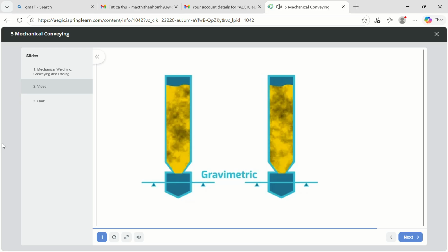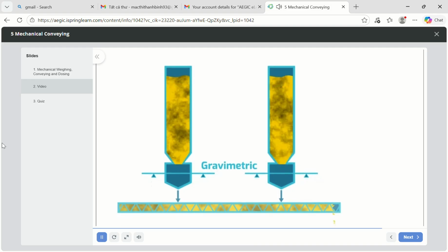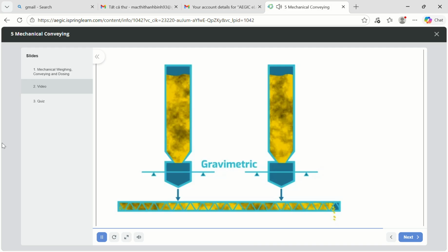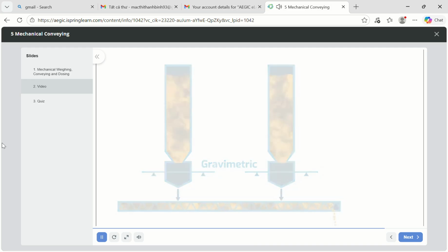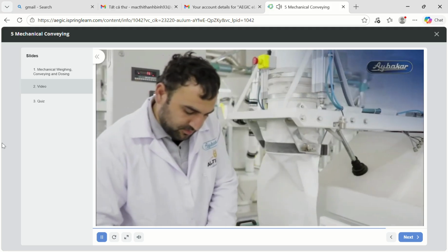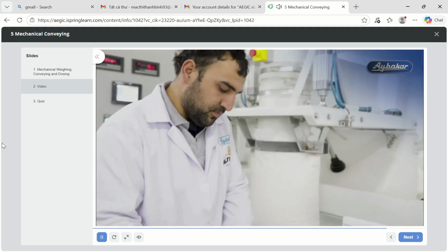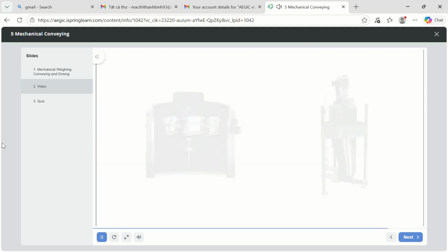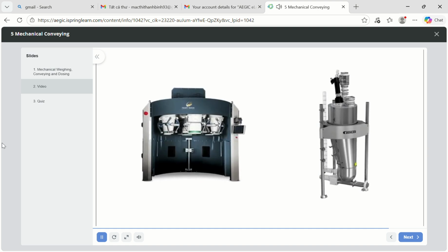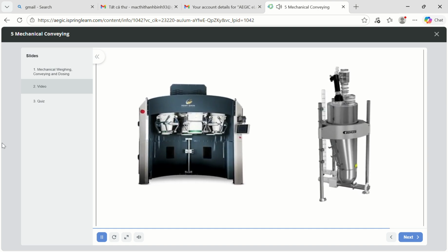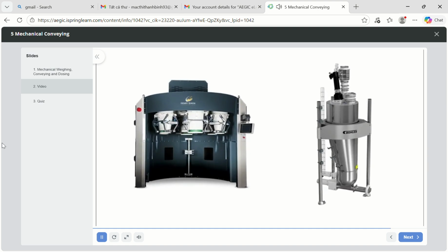Gravimetric dosers, in contrast, are less affected by changes in material density because they're dosed based on weight rather than volume. Examples of their use include mixing operations or dosing flour to fill flour bags. Some designs use scales to measure flow rate based on weight lost over time.